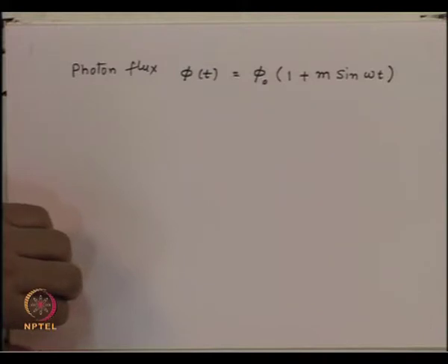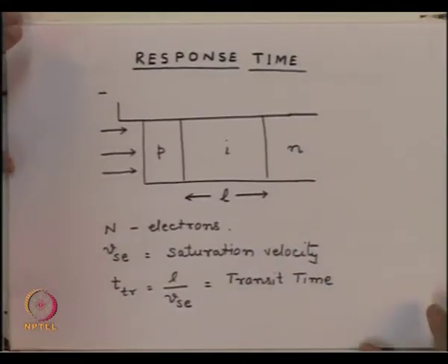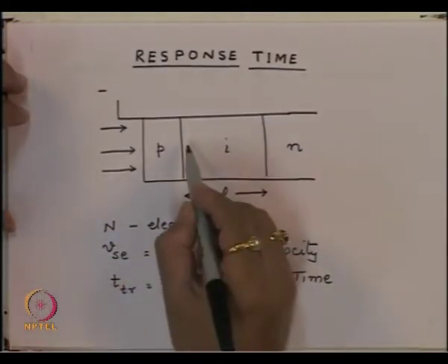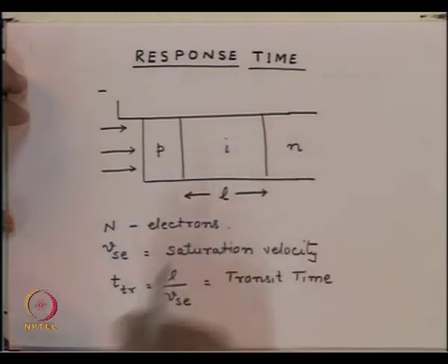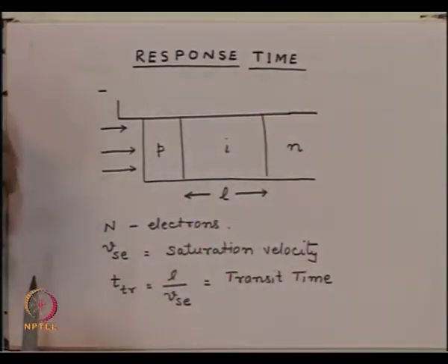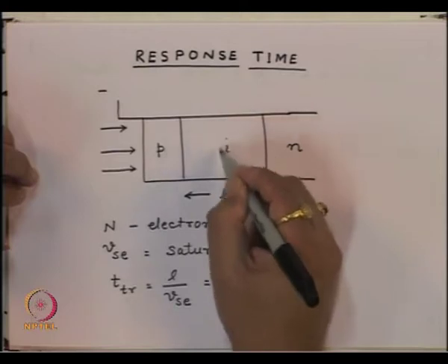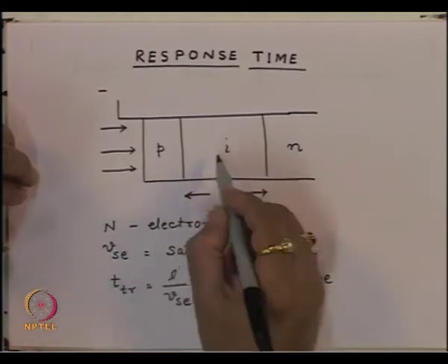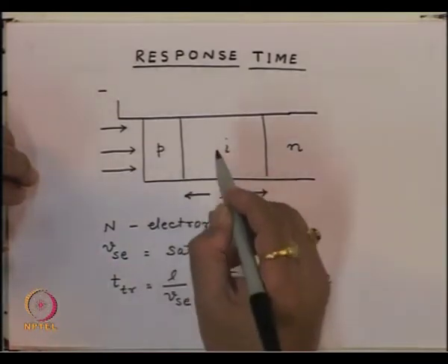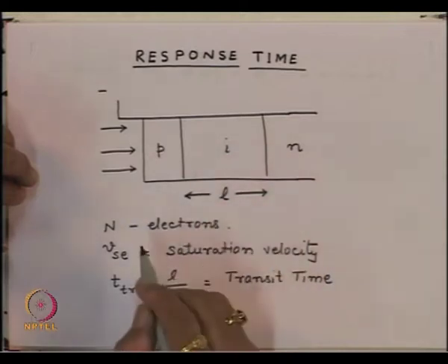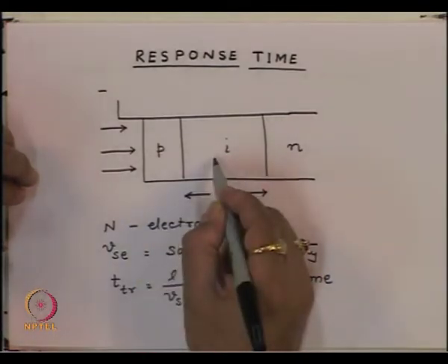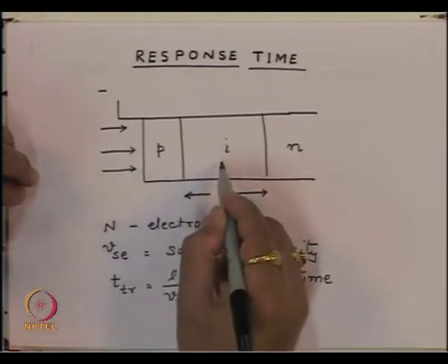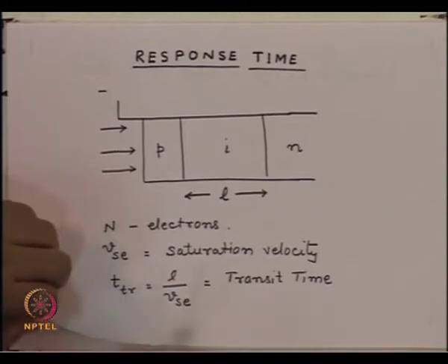So let us see now that when this signal is incident on this, and let us assume that the carriers are generated uniformly in this region for simplicity. If we consider any small section in this region, we will see the carrier passing through that, which will be the carrier generated at that instant of time in that region, plus all the carrier which were generated some earlier time in these layers and now have traveled to cross through this particular layer.